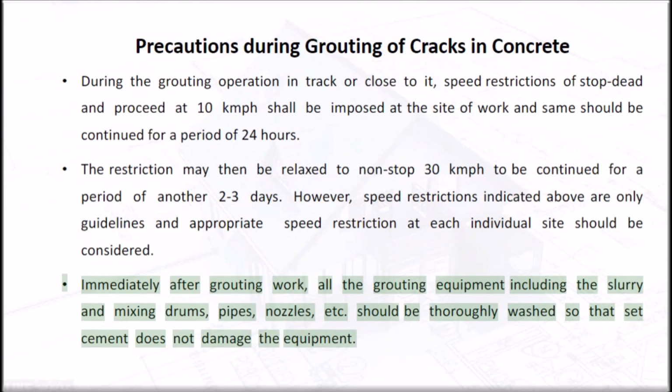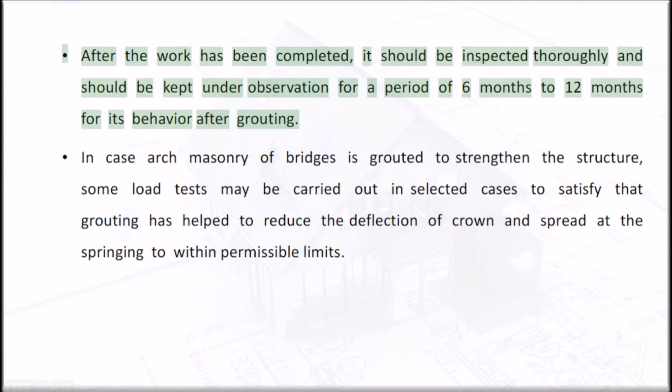Immediately after grouting work, all the grouting equipment including the slurry and mixing drums, pipes, nozzles, etc. should be thoroughly washed so that set cement does not damage the equipment. After the work has been completed, it should be inspected thoroughly and kept under observation for a period of 6 to 12 months for its behavior after grouting.